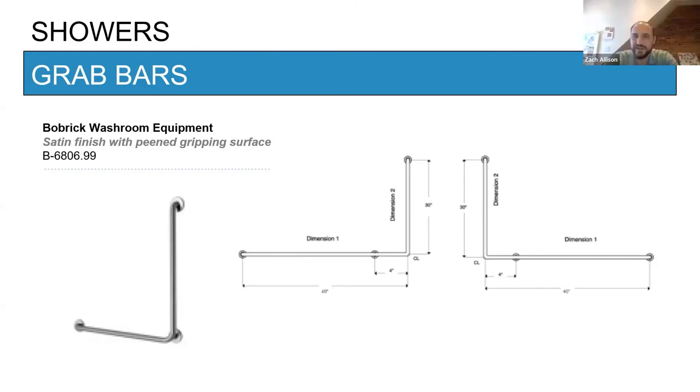Yeah, I think one of the questions that's really been coming up more is on something that we might have missed on a slide earlier. There was a question that's come up a couple of times regarding the components below a lavatory. One thing I will say is that prevention against knee contusions is a requirement of the code for the lavatory area. That can be handled one of two ways, which, similar to the backrest, is not specifically mentioned in the details. It just says you have to prevent against contusion and scalding.